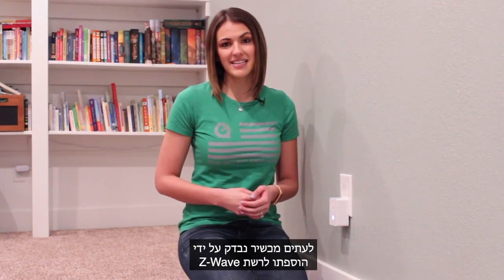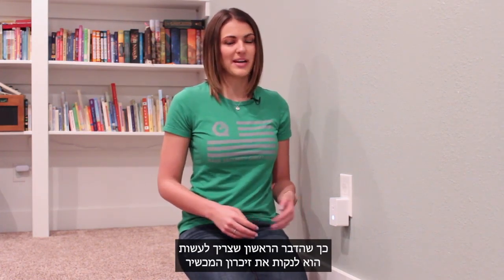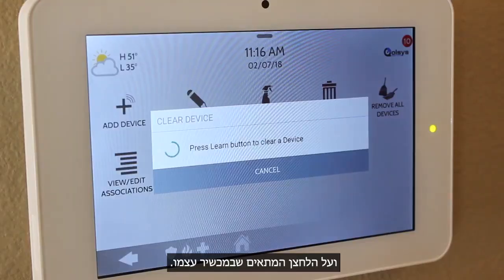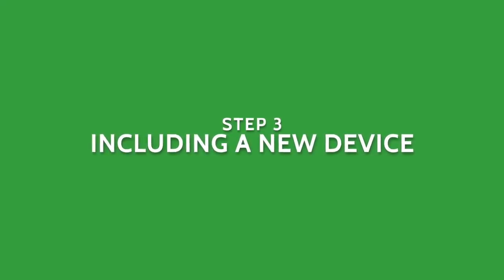Sometimes a device is tested by being added to a Z-Wave network before it leaves the factory. So the first thing you should do is clear the device's memory before attempting to add it to your network. Simply press clear on the panel and the corresponding button on the device itself. It is deleted from the network successfully.